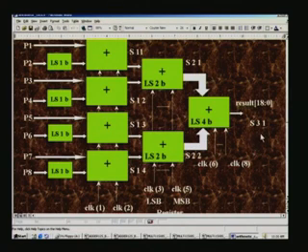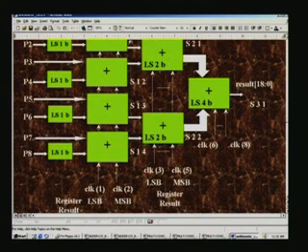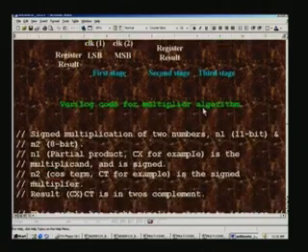What is important is how efficiently we do it. You can see here the partial product is shifted 2 bits in the first stage, and in the final stage when you add the 2 numbers, once again there is a left shift of 2 bits for the second number. So is the case here: when we add these 2 numbers, the second is shifted by 2 bits, this is the second stage input, and for the final stage we see that it is shifted by 4 bits, for the reason we have explained. And finally the result is 19 bits, as we have seen before. So this explains the algorithm, and we will look into the Verilog code for this algorithm.